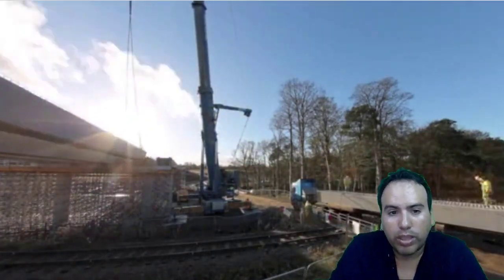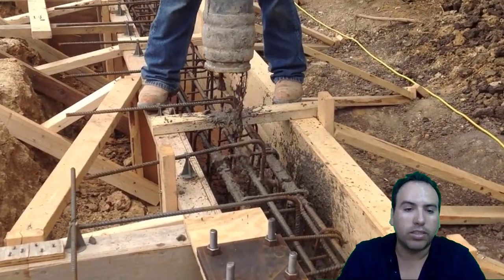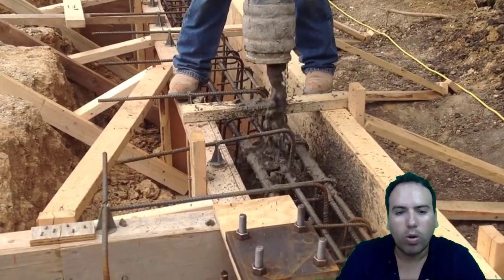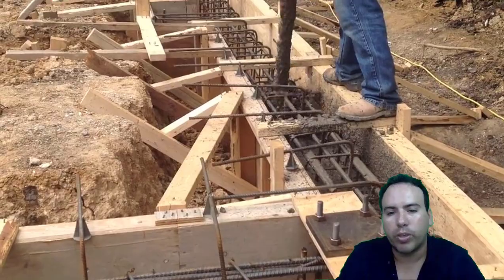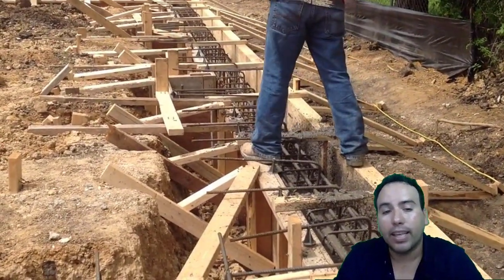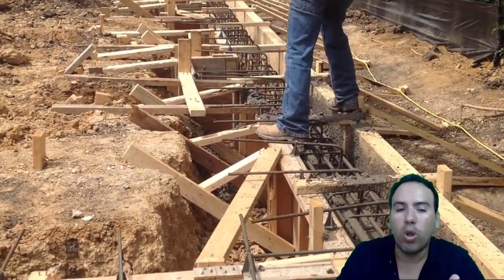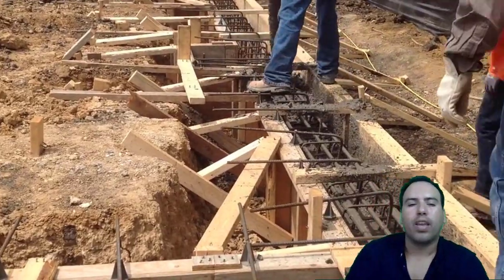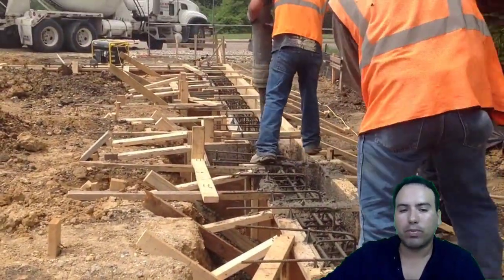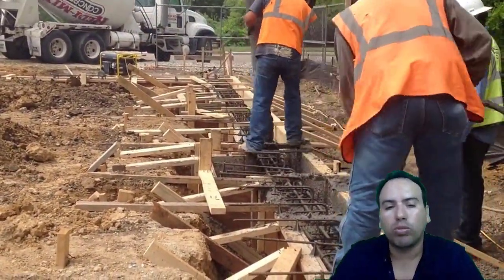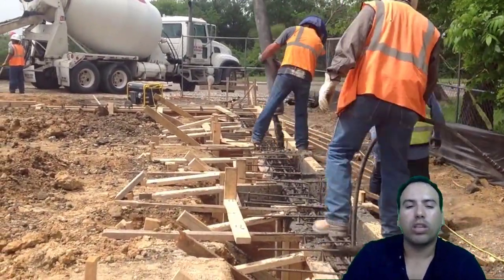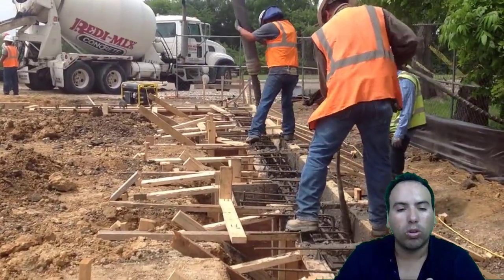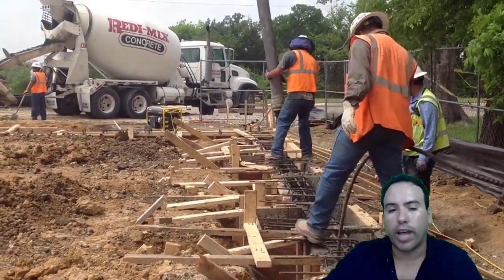And when it comes to the types of loads on the beam, it's pretty much the self-weight of the beam, the dead load that includes point load, for instance, a column constructed on beams, distributed load, for example, slabs set on the beam, the live load, and the torsional load. The load transfer mechanism in beams: they transfer the loads imposed along their length to their endpoints, where the loads are transferred to either columns or walls or any other supporting structural elements.